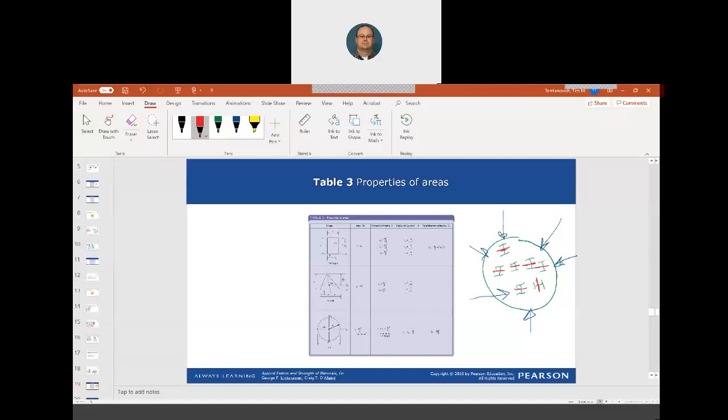However, when I did what's called an L pile analysis to figure out how big this steel I-beam had to be, I assumed the moment of inertia value I used for my design was for rotating about the YY centroidal axis, which was the weak axis. So it did not matter which way the piles were rotated, which was great. Granted, I needed more piles because they're less stiff, but it eliminated a lot of confusion. So that's kind of where this comes into play.